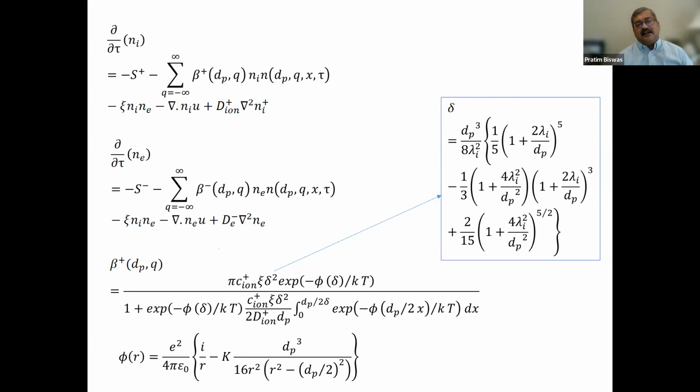So as a result, the strategy was, could I impose a simplistic electric field? By no means optimized. I could definitely optimize how I apply that electric field. And that's why the negative bias field to remove that. So it's as simple as that in some sense. And once I remove the positive ions, the charging efficiency goes up because they can't act as a neutralizer for the charged particles, especially the negatively charged particles, as they go into the afterglow region downstream of the plasma zone.